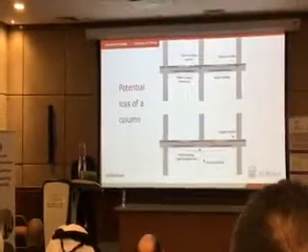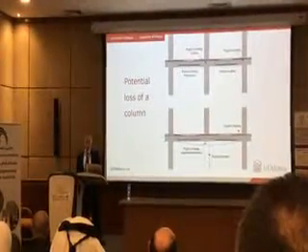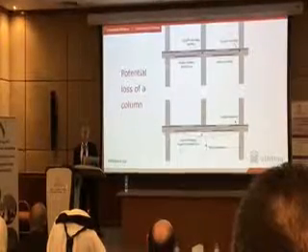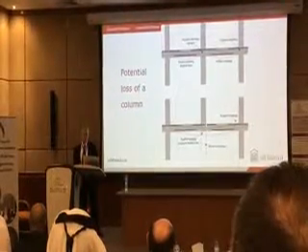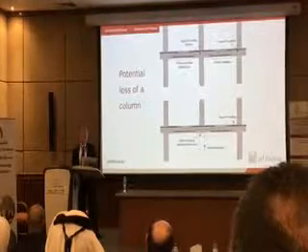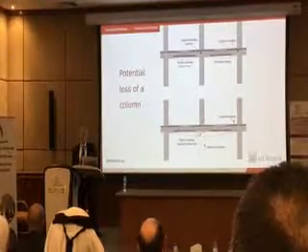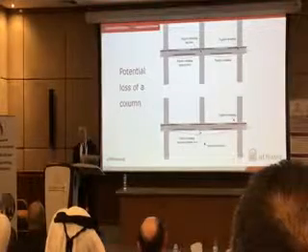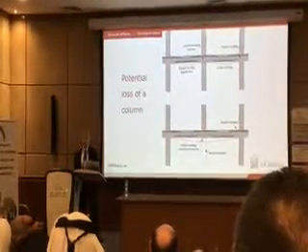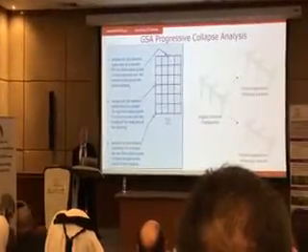But if you remove this column, then of course you have positive moment for which you did not provide reinforcement, so then the whole thing may come down. So what we do is we provide the integrity steel, so even if the negative moment region develops positive moment, it remains intact, and there are also retrofit techniques for that.